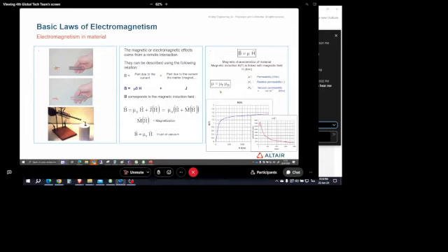And we don't want to use plastic or aluminum for canalizing the magnetic field. So we need to use this material for its mu r characteristics, but we don't want to push it to the maximum, otherwise it will be like air or vacuum from a magnetic point of view.